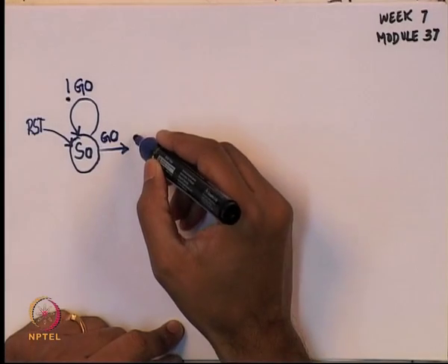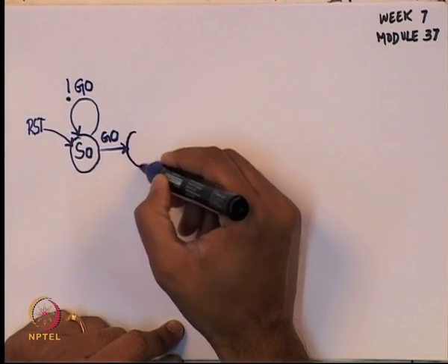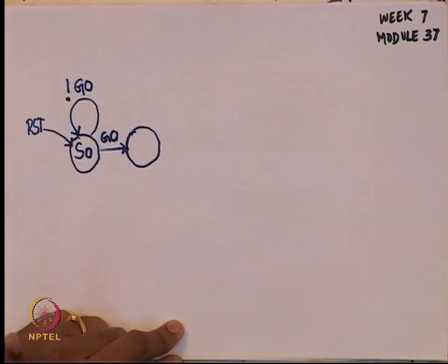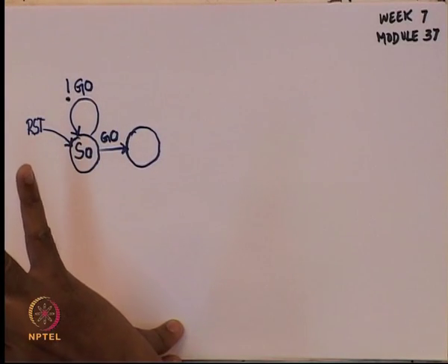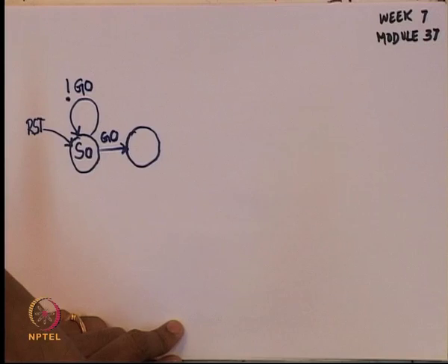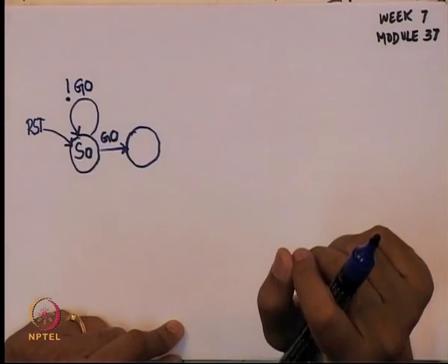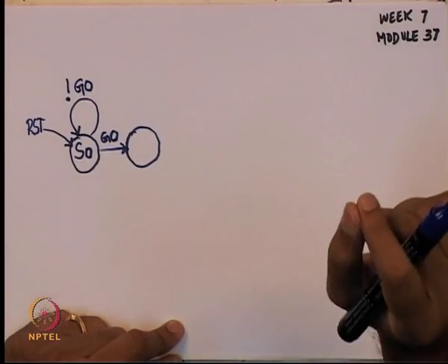So, what is it supposed to do now? This controller, if go is on, I assume that the inputs are going to remain stable from the external world, and you got the go signal from the external world, which means the first thing that the data path must be doing is take the values from the in1 and in2, and it is supposed to put it in the registers A and B. To be able to do that, let us look at the data path's picture.